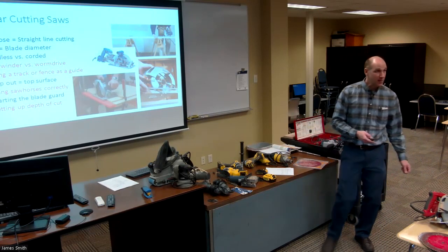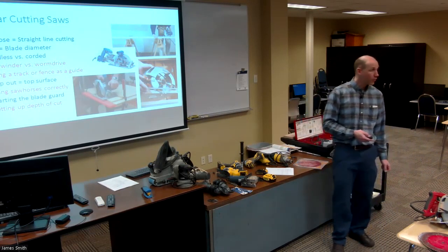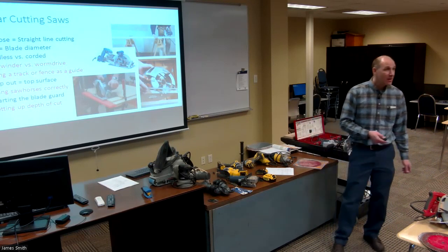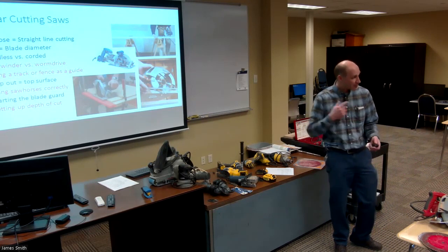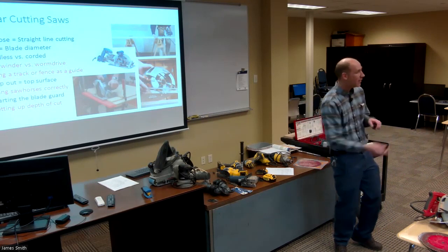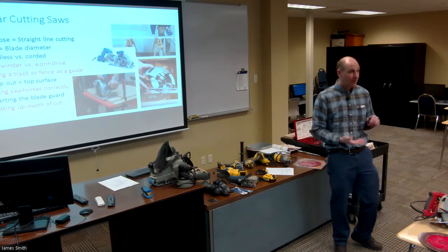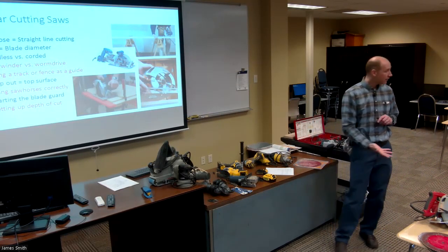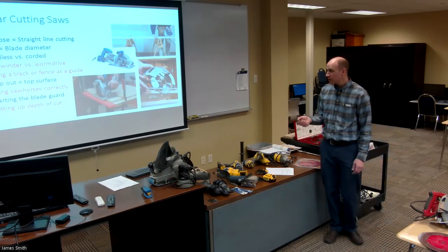I guess the last time I priced out plywood was about $110 for a sheet of 3/4 inch birch plywood. So before you cut into that, make sure that the good face is facing down, so that as the saw cuts up, it chips out on the back side, the poorer grade of the veneer, rather than the nicer grade. Okay, that's what I'm talking about as far as chip out.